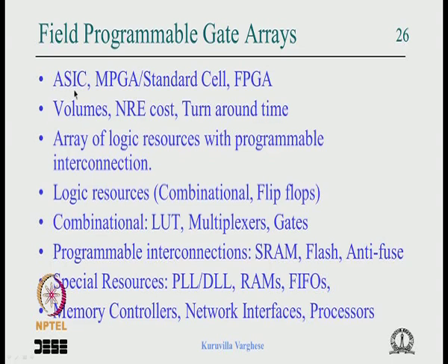So the trouble with ASIC is that since it is more or less designed from scratch, the NRE cost will make it viable only for huge volumes, and it takes 1.5 years from start to end for a reasonable complexity ASIC to come to production. Okay. So this is one feature of the ASIC.